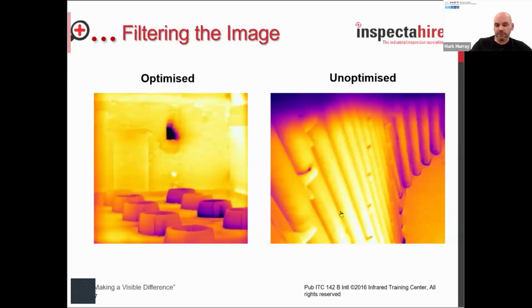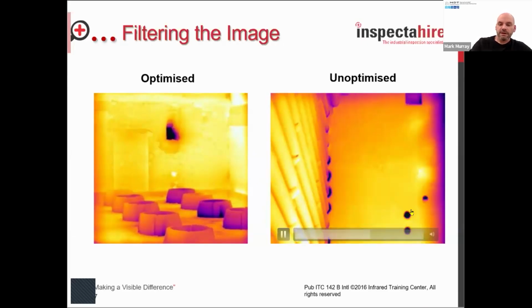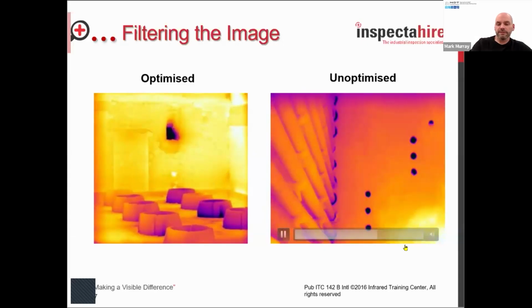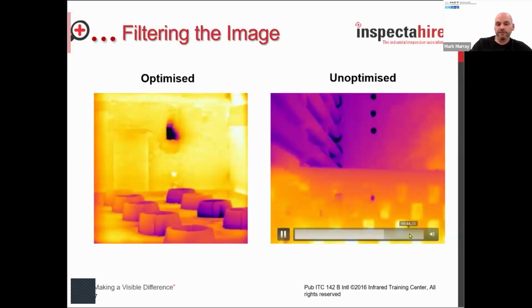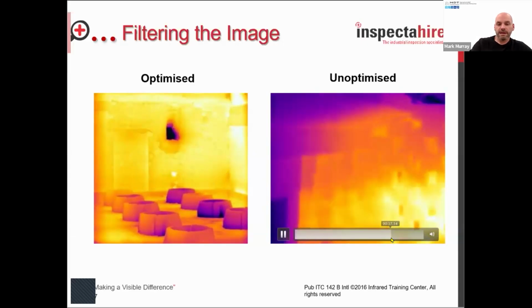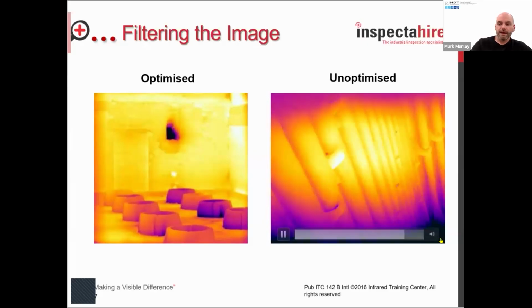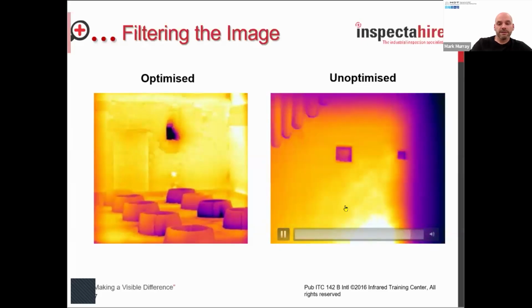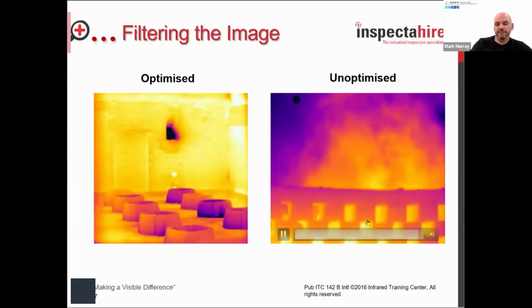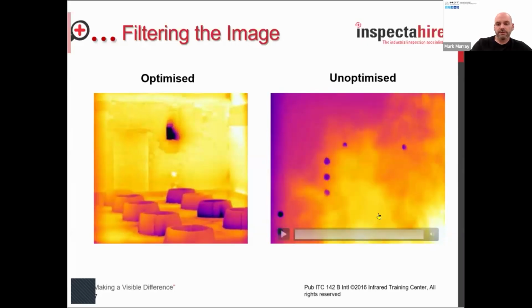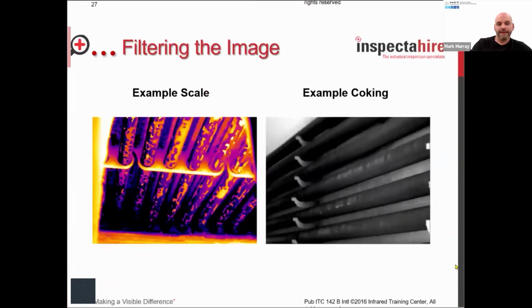On the unoptimized side, of course, we're able to see the flames, and these can make an incredible difference when you're trying to measure any sort of temperature, and you just can't measure it, basically. It's almost impossible. And this is due to, it could be dirty fuel or unoptimized burners, that type of thing. But there's lots of things that can affect it. But what we're looking for is an optically resolved image, as we see on the left.